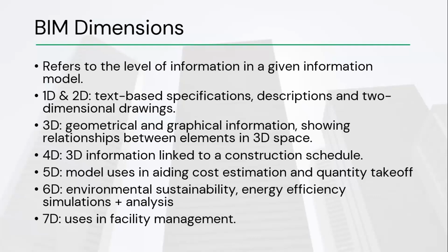But then BIM, as we are looking at it, developed from the advancements in 3D CAD, which made the model that is developed from 3D a dynamic one. Dynamic means that if you look at the other process, you had to do your floor plan. When you are done with that, you do the elevations independently, you do the sections independently, you do the details independently. You share that with the QS to do the takeoff independently.